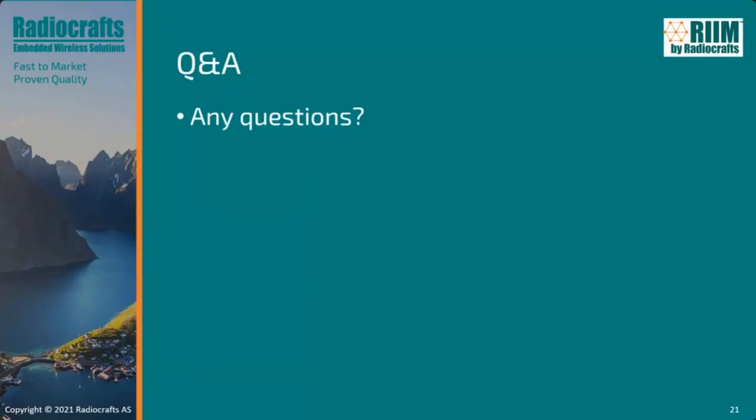Magnus also asked about sleeping devices and battery drain. Can you broadcast messages to sleeping devices? How often do sleeping devices poll their parents? Basically, the polling is something the user can configure. You can choose to poll every second or 2 seconds, or you can poll every hour if you want to. That depends on the use case, how much battery you have, and what type of latency requirement you have in each use case.